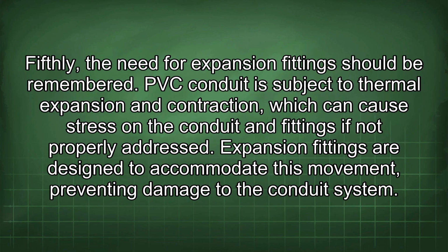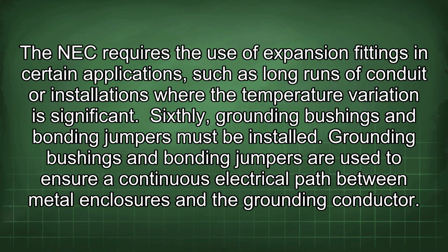Fifthly, the need for expansion fittings should be remembered. PVC conduit is subject to thermal expansion and contraction, which can cause stress on the conduit and fittings if not properly addressed. Expansion fittings are designed to accommodate this movement, preventing damage to the conduit system. The NEC requires the use of expansion fittings in certain applications, such as long runs of conduit or installations where the temperature variation is significant.